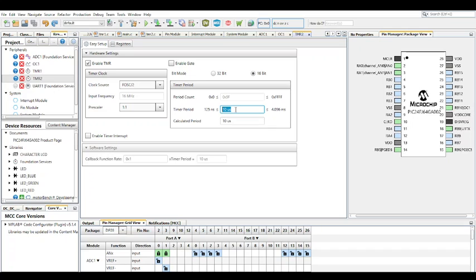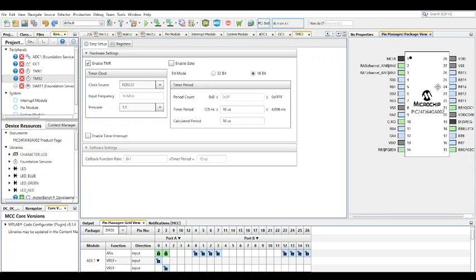What I mean is, how often are you changing the duty cycle whilst you're doing the closed loop control? Because this is 10 microseconds, we could literally make that loop as fast as 10 microseconds. Obviously, this microcontroller is not designed for this purpose, so we can only go as far as 150 microseconds.